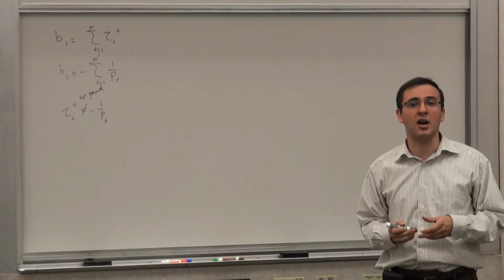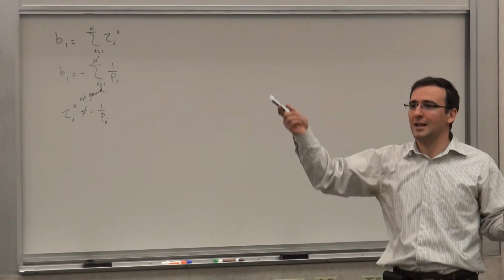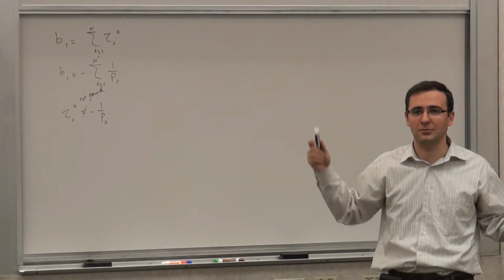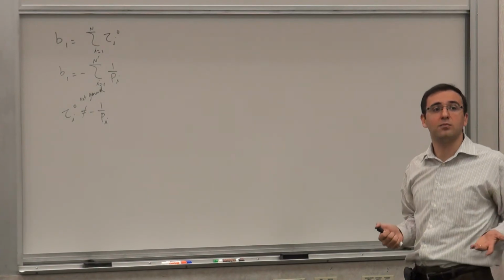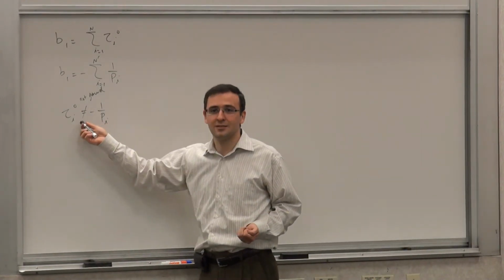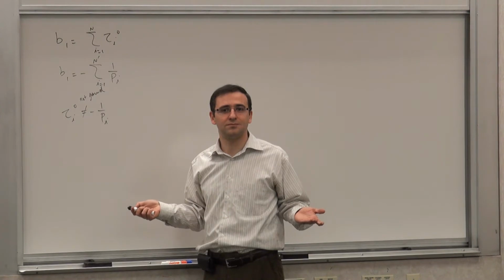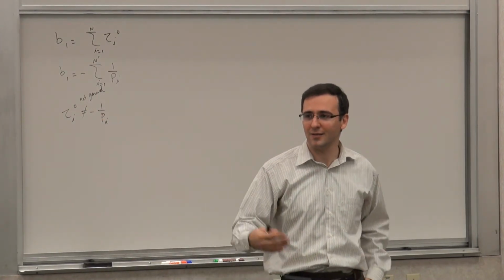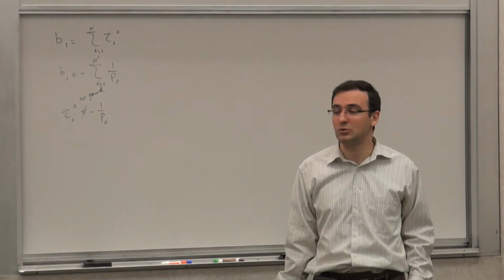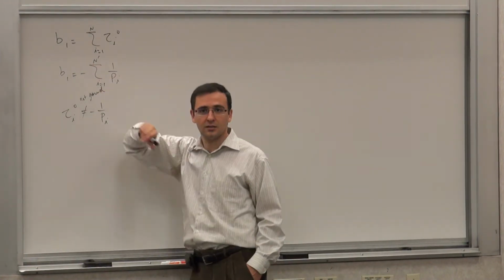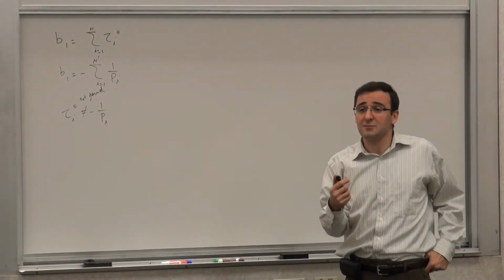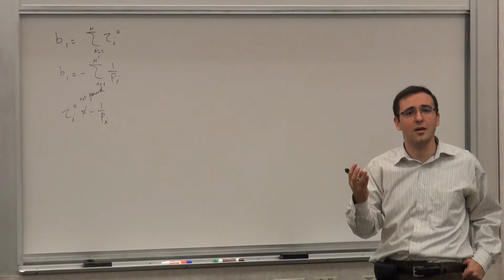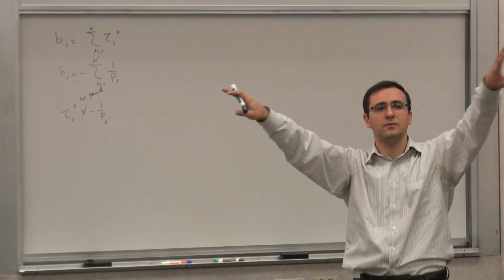Several reasons for it. First of all, the numbers may not be equal. You know, in that example, you have 2 poles and 3 time constants. Right? In the previous example. Second is that the poles can be complex. Time constants are always real. So it's difficult to have a complex quantity equal to a real quantity. So it's obvious they can't be equal. Their numbers are not equal. That's why I use n and n prime here. But there are certain special cases where they are. And that's when a time constant or a set of time constants is decoupled from the rest.